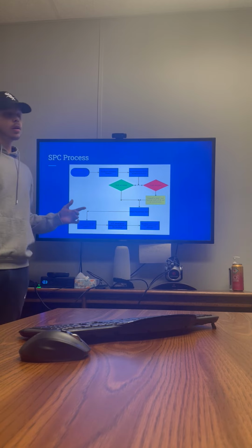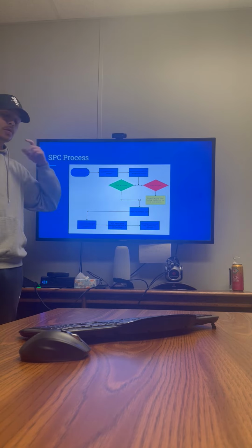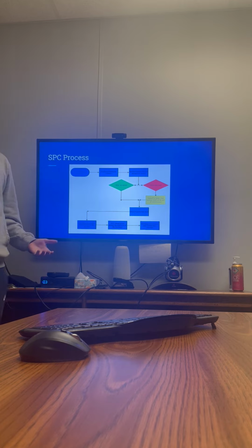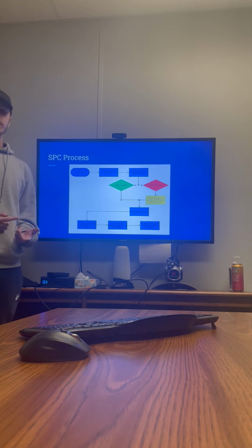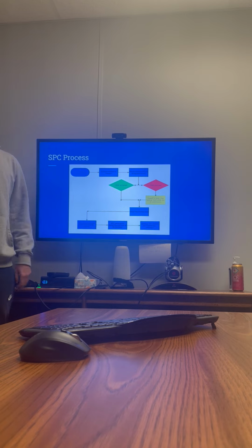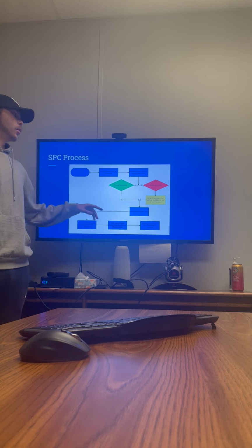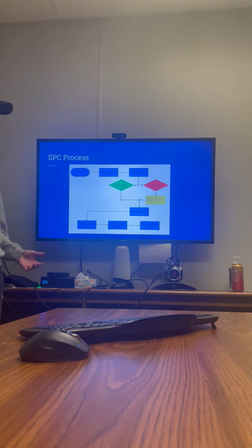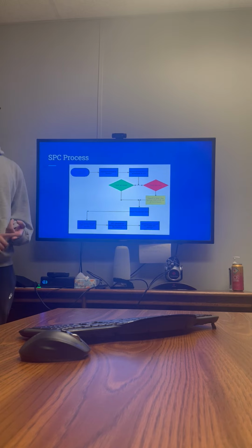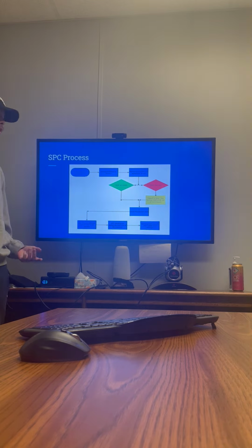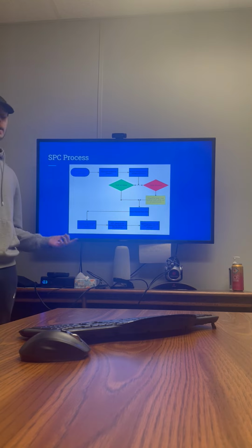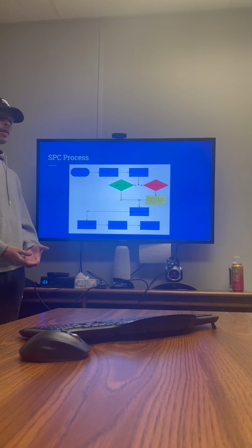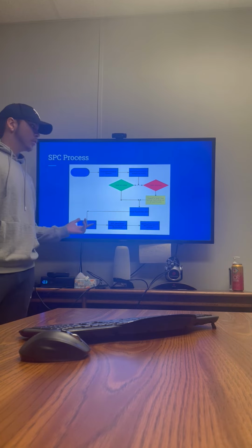And then there is a worker that has to go and check if the mold is acceptable. So if it has any dirt, cracks, and stuff like that, it could cause impurities in the bushings, so the worker needs to check that. The worker will either accept the mold or decline it. If the worker declines the mold, that mold needs to go and get fixed or cleaned depending on what is wrong with it. And then a backup mold will be brought in, which will have to be checked again by the worker to make sure that it's good to be used.